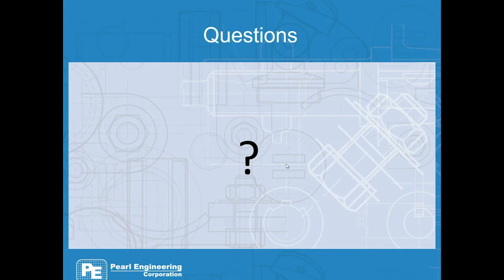Oh, looks like we have another comment from Steve Abbott. He looks like he knows where his next tube leak is going to be. It's going to be on the handhole cap bolted on the square header. That is pretty common. I don't know why that design was as popular as it was, but square header handhole caps, I have seen those leak a lot. So thanks.